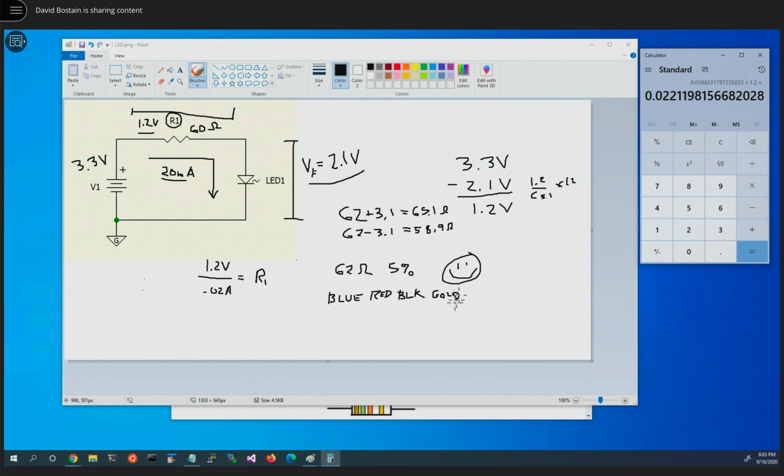So it's perfectly okay for this resistor, at least for the tight end, to have been 1/8 of a watt. But remember, we don't care about that. We care about when it has the most current, which is here. But we saw that this is going to have roughly 18 milliamps as a minimum. That's enough to turn the light on. So let's do the other calculation. 1.2 divided by 58.9. It's going to be 20 milliamps. That's definitely less than 25. So it could be as high as 20 milliamps.